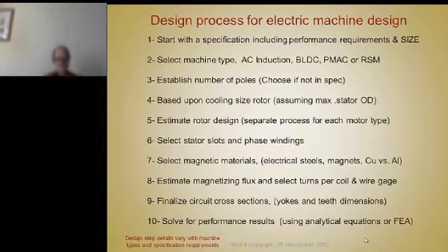Well, when you do that, a big problem, a big design problem, a quality problem comes about because the current, if the current is not shared, if I have 1 turn per coil and I have 10 strands per turn, I have to have 1/10 of the current in each strand to have equal current density, or the lowest current density in the strands. But if for some reason or other, and there are a number of reasons why current will not evenly distribute itself through the strand, parallel strands, that's a design problem to deal with.